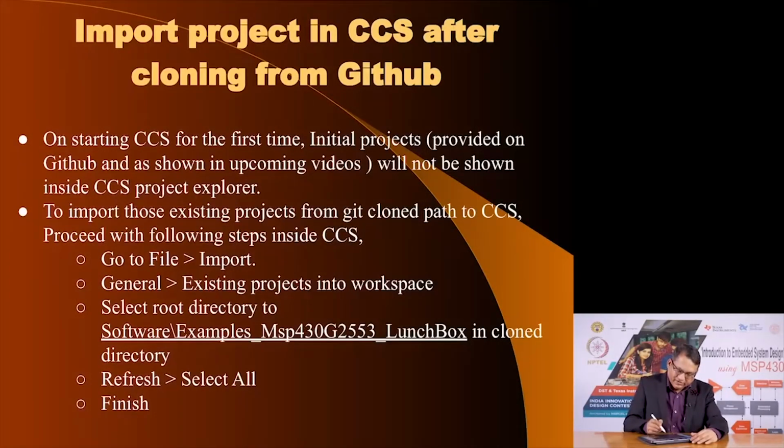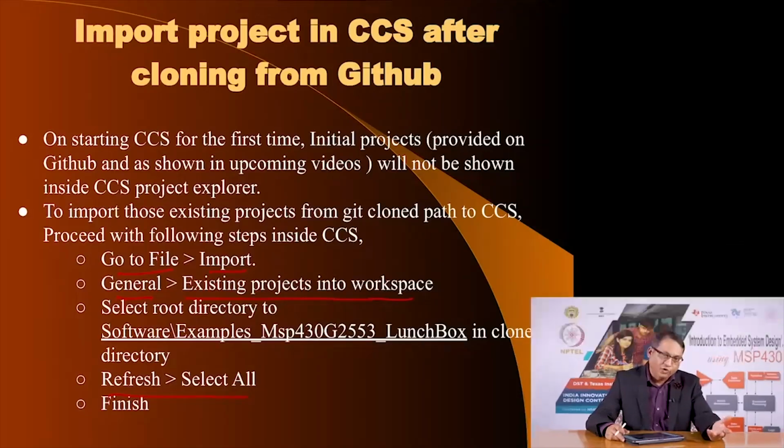To import existing files, you go to File, Import, and in the tab it will show General, and then you say that you want existing projects into your workspace, and you need to point it to the right directory, which would be in that folder that you created. Once you do that, you refresh, select all, finish. Now you are good to go. Code Composer Studio would know all the code folders that we have created for you. They are already on your computer, but now Code Composer Studio knows where they are and that you want to work on them.